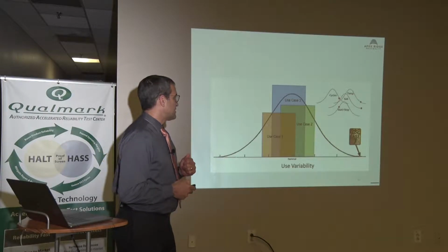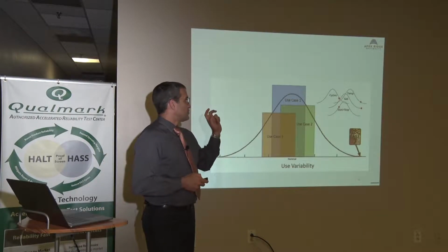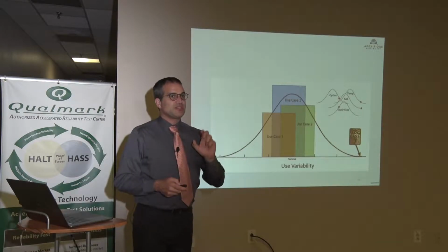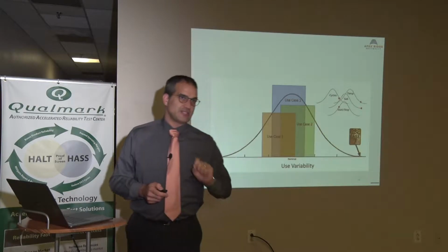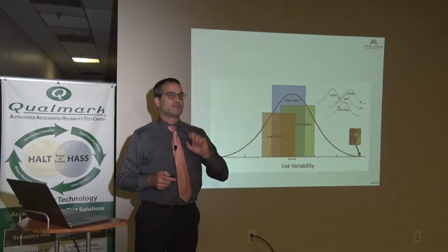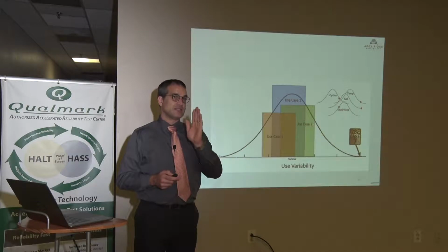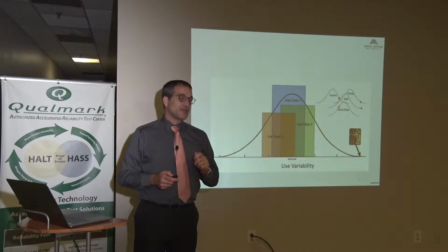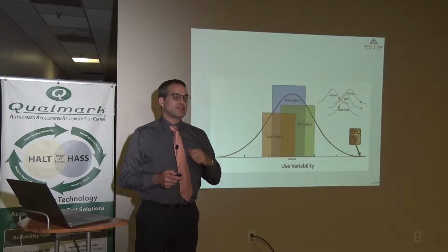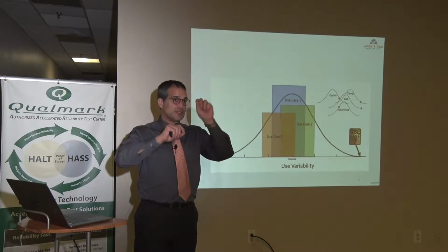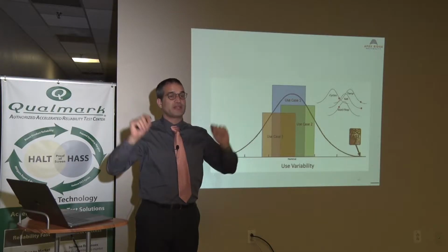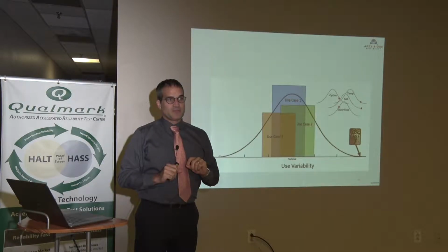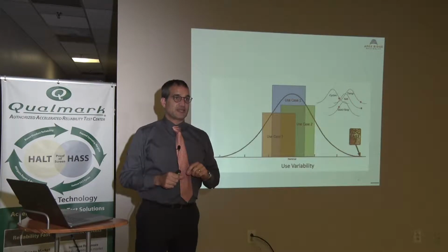So use case 7, the idea is that we create a use case that effectively doesn't exist. It would be very unlikely, it would have to be a race car driver to take all these things to the extreme, right? It would be an off-road race car driver to take them all to the top in the same use case. And that's why it's unique: you are taking those combinations of stresses that usually you take some up and some down, and you're putting them all at levels that can really be done, but that are all high in combination. So now you're also getting that effective design of experiments of combined stresses and what can occur.